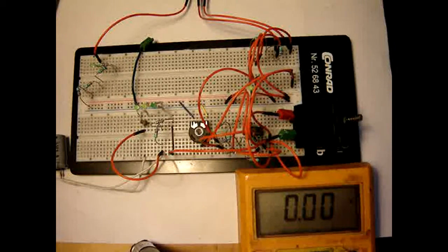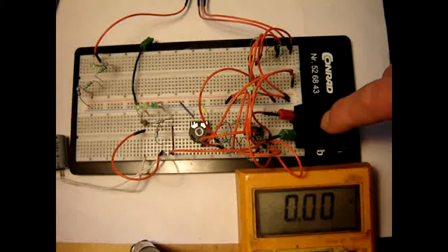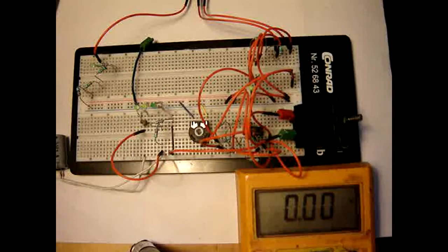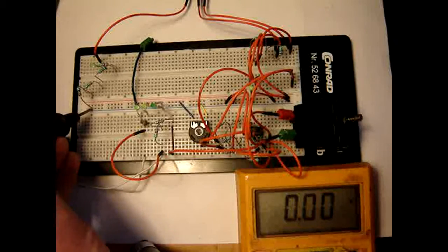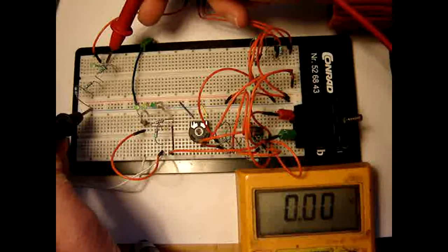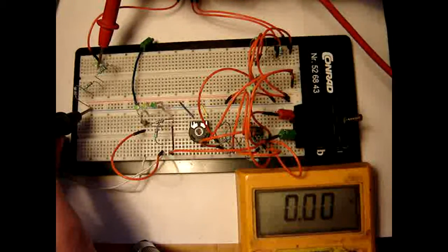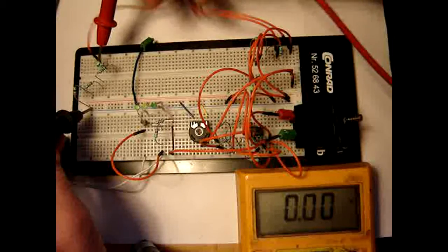So what I'm going to do now is try to figure out why this assumed pulse width modulation motor is running constantly at 5 volts, which is coming from here and can be regulated by this potmeter. To show exactly the values, the mass probe goes here for now, and then I measure at this point, and it says now 0 volts.